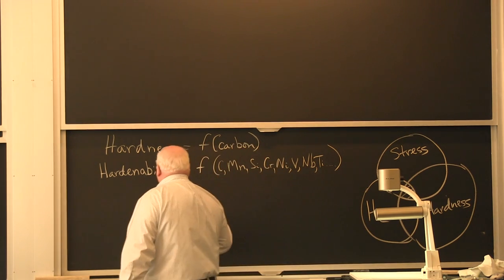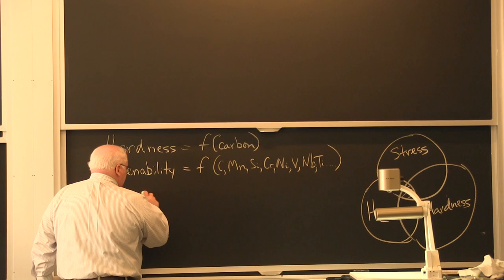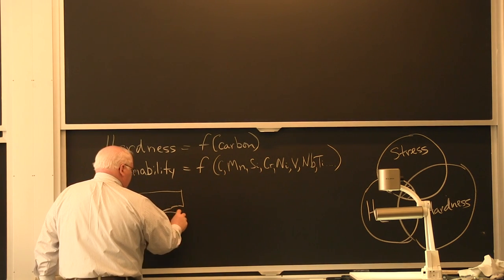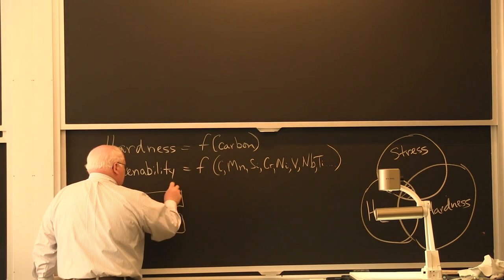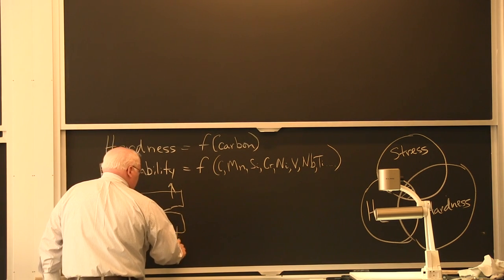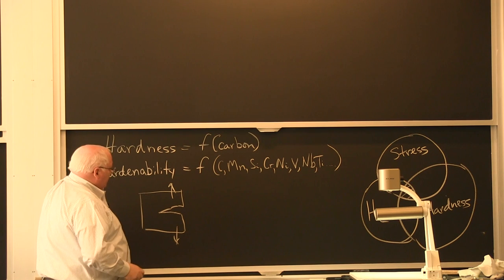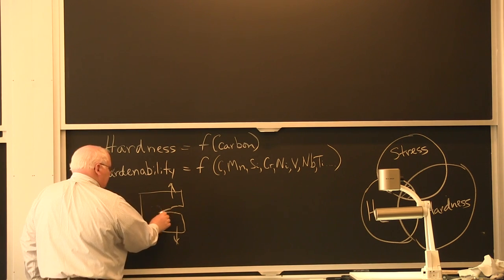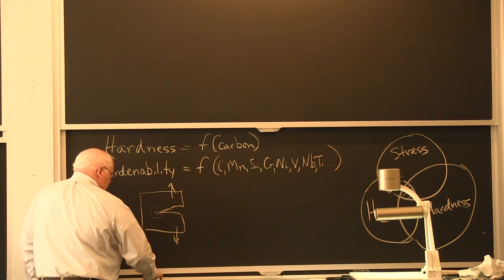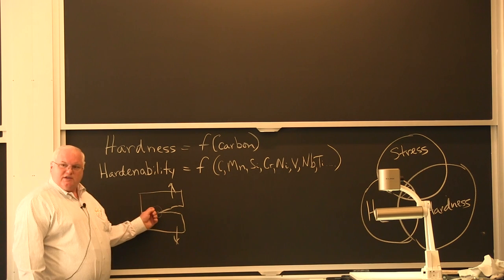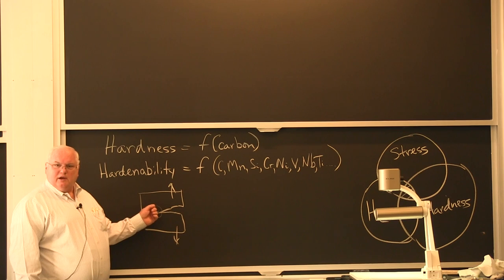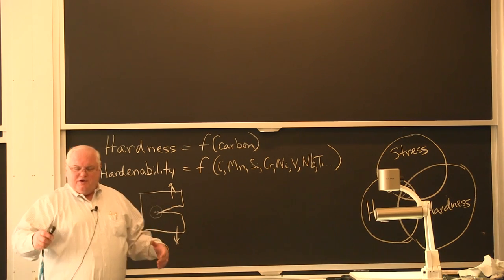It turns out sometime back in the 1970s, some people at Rensselaer Polytechnic took a piece of steel which they polished, and they had it so they could stress it, and they had a crack in it, and they immersed it in water and put it in a microscope, and they looked at just the cracked tip, and they could see bubbles coming out. As they increased the stress, they would see the hydrogen bubbles come out with greater frequency right at the cracked tip.